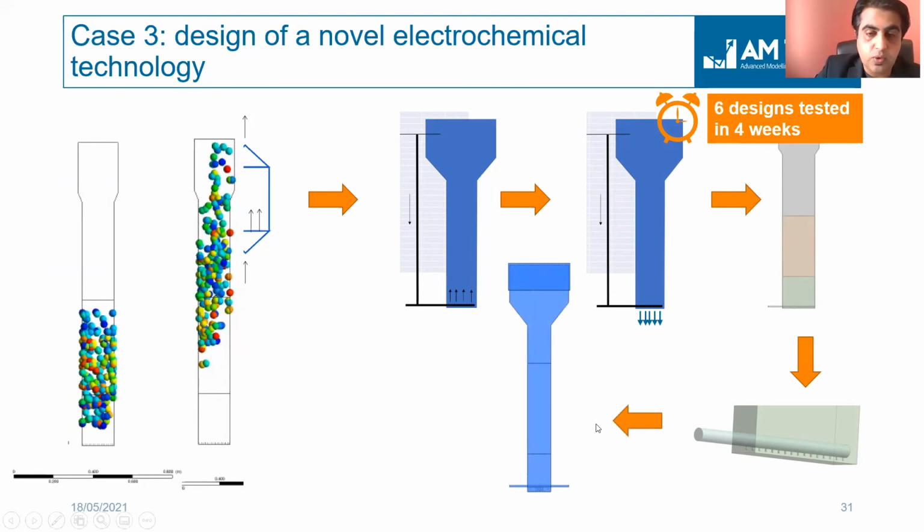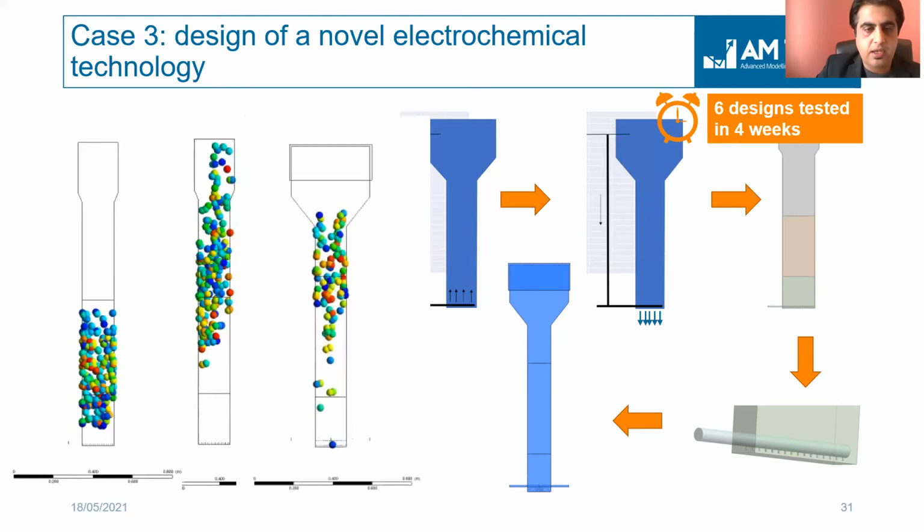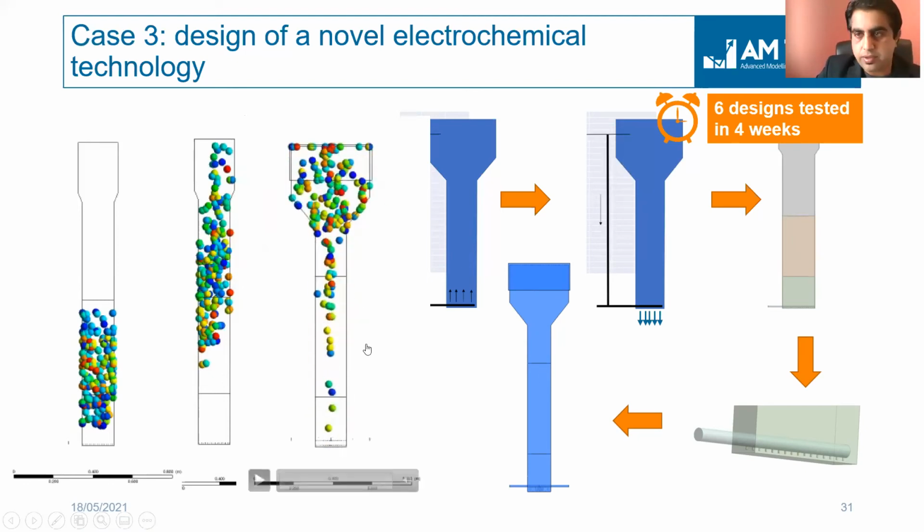the particles. So what we did in that case was we changed the inlet structure further. Instead of bringing it from one side, we brought it from two sides, had a baffle in between, still pointing downwards, and tweaked a bit of the incoming flow, and then we eventually saw better distribution and better particle fluidization in the reactor.